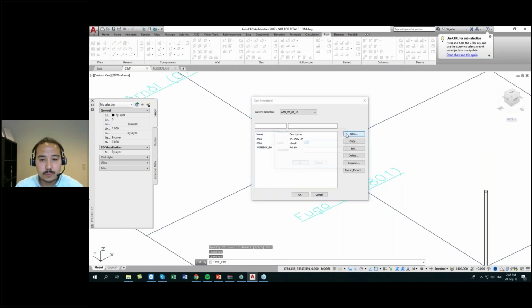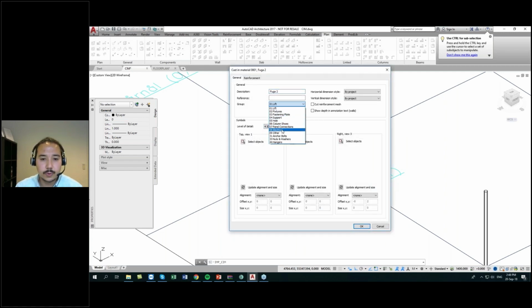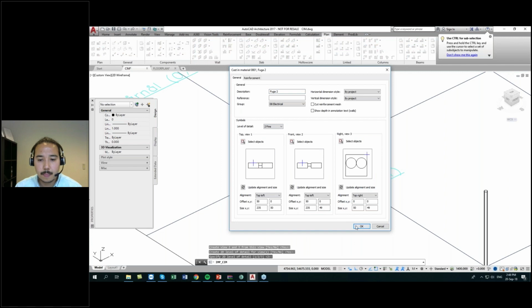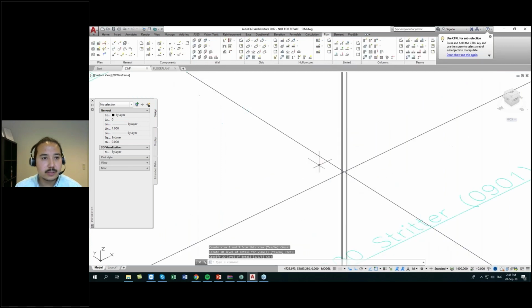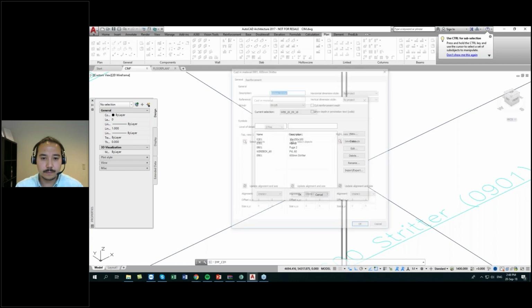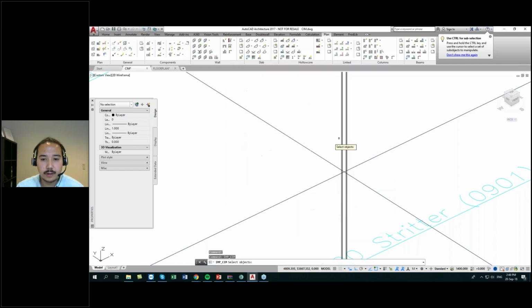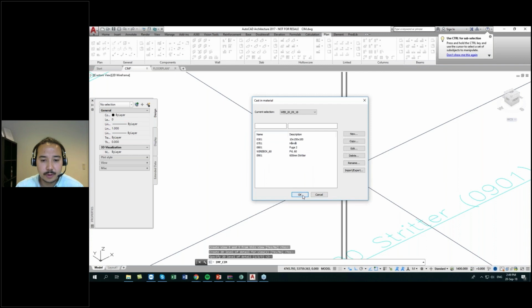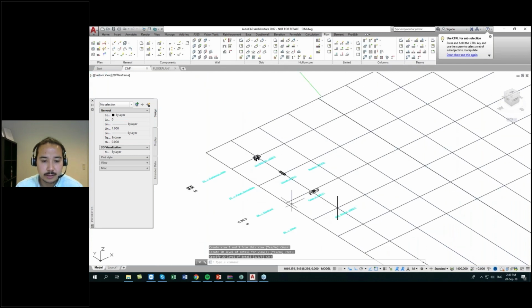And we will just do 0801. Put in here on the electrical. Select all the components and create the other views like this. And last but not least, this one here, 0901, 600 millimeter straight on. And this one should be put under other, and let's select the insertion point. And I want to create all the other views from it also. So now I have put all my manually created custom materials into the database.